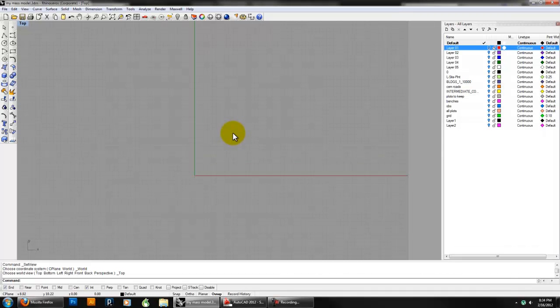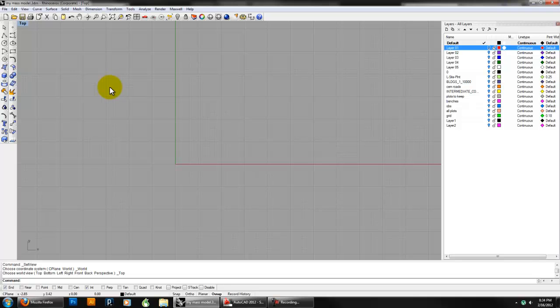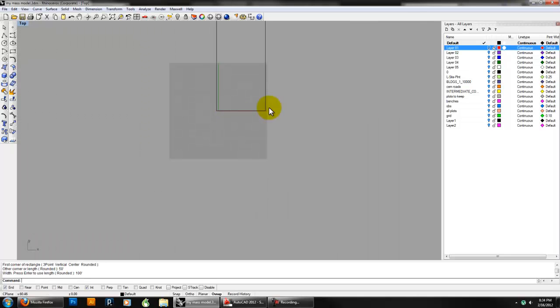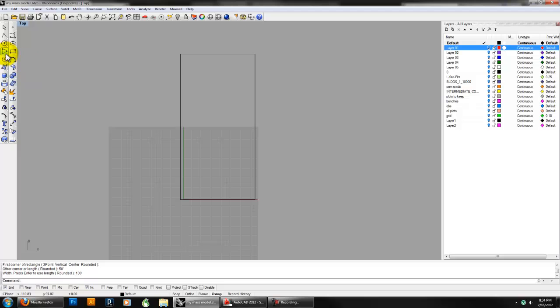So you could take your lines from AutoCAD, or since you're working on your second twin, you could begin actually massing things in AutoCAD and in Rhinoceros, and you could do that by going to the rectangle tool, and you just specify first corner of the rectangle, fine, and then you can say the length of it. The length could be 50 feet, 50 apostrophe, and the width could be 100 foot, 100 apostrophe. Right? So that gives us our shape.